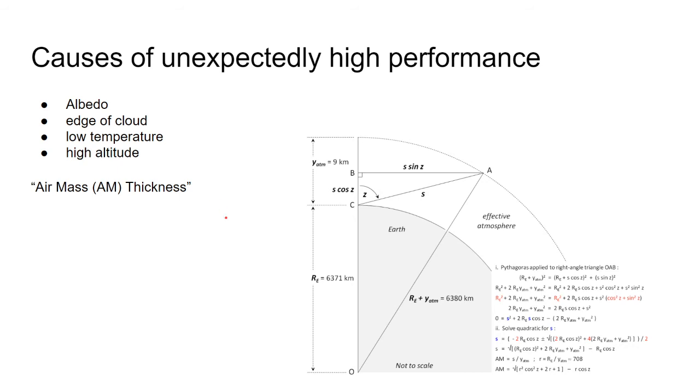Again, that's not usually a very big deal because with solar conductors that are very long, you're often oversizing anyway to accommodate for voltage drop. But it can be confusing because you'll end up with large circuits that can carry 30, 35 amps, and it's only a 8 amp circuit. So that to an electrician that can be, well, why is this so oversized?